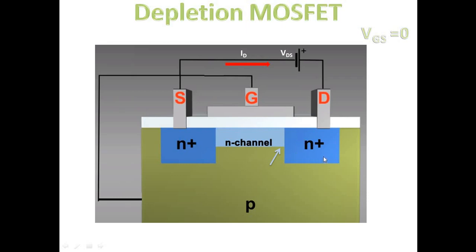So in this situation, a similar kind of scenario arises as in the JFET, because as you go on increasing VDS, this particular biasing creates a depletion region which expands on both sides of the junction. This depletion region goes on increasing as you increase VDS. So the current increases as you increase VDS, but the depletion region also grows inside the substrate as well as inside the N channel.